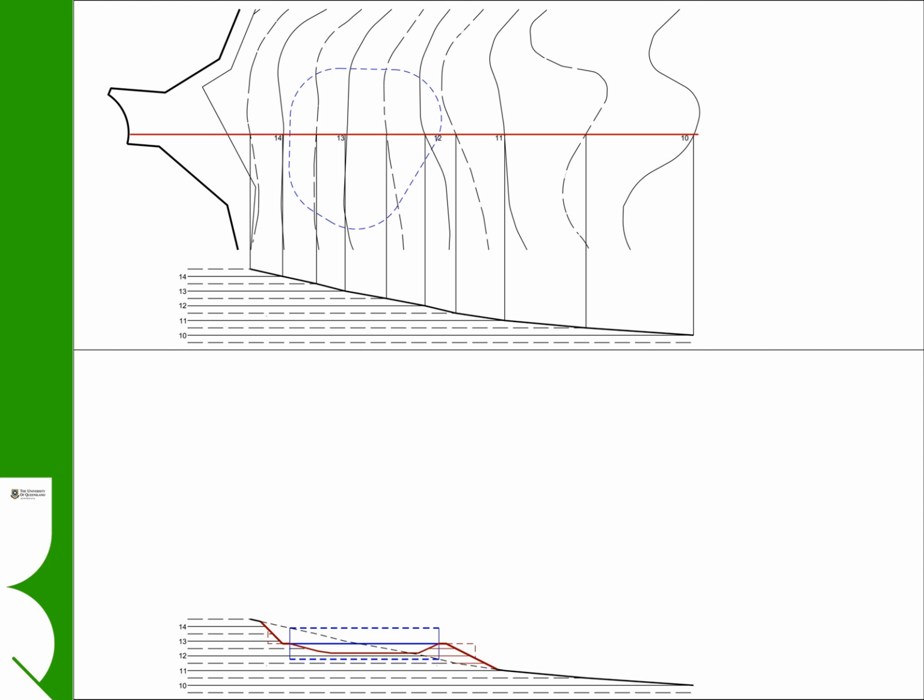Because excavated or cut slopes can be more stable than filled slopes, our advice in this instance is to make sure that the slope of the cut side is not steeper than 1 in 1. That is, that the slope rises 1 meter in height for every 1 meter of horizontal distance. The filled slope, though, should be set at 1 in 2. That is, that the slope rises or falls 1 meter for every 2 meters of horizontal distance.